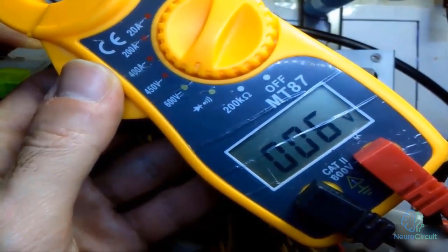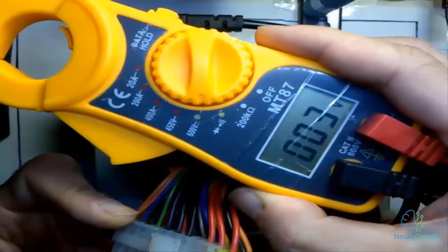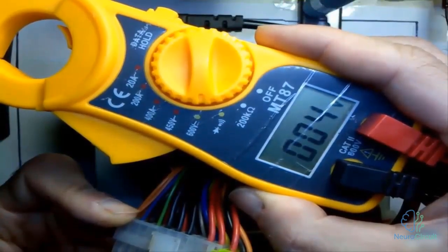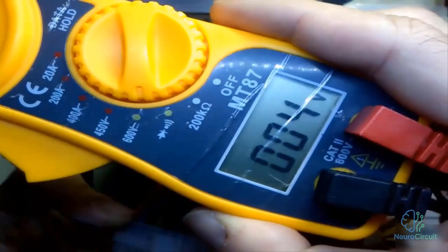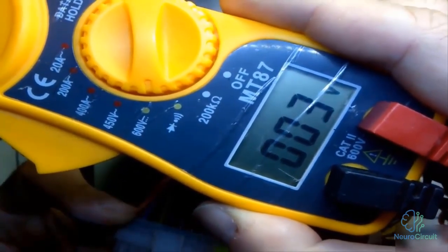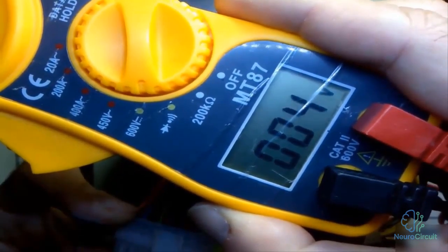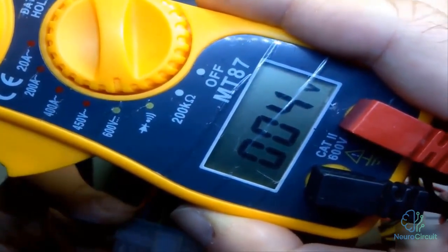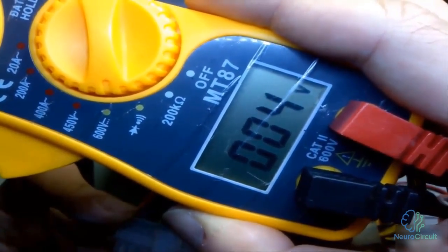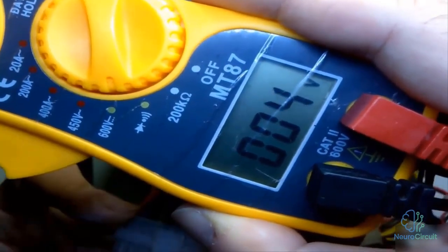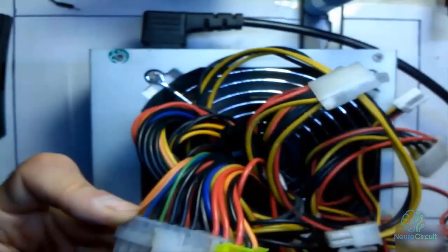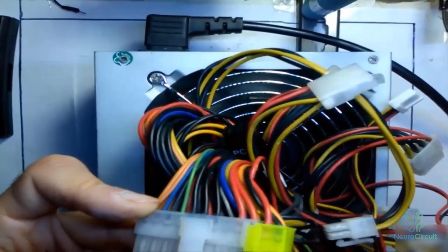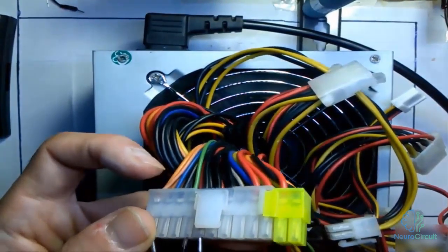Alright, now let's test the 3.3 volts. Here as well, you can see the 3.3 volts, and in fact the voltage is appropriate and the output voltage of this power supply is completely stabilized. As mentioned before, the small error you see here could be due to the multimeter, and even if there is an error, this error is permissible. All components and devices have an allowable margin of error, and this does not cause any problems.